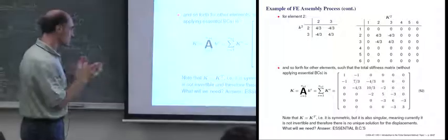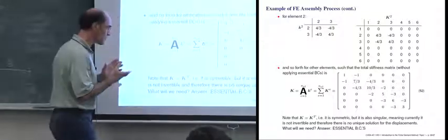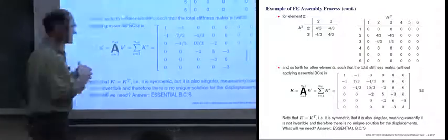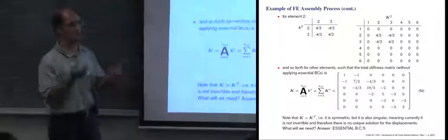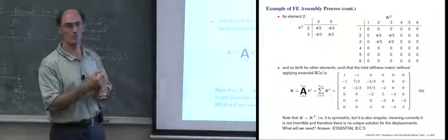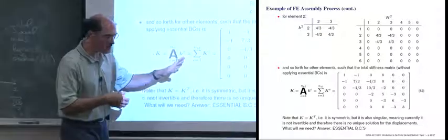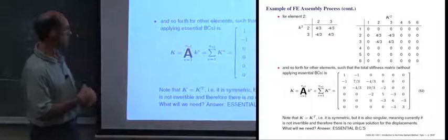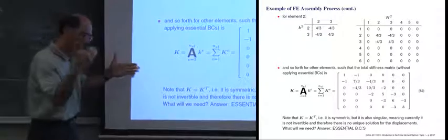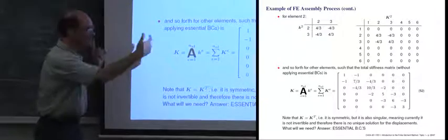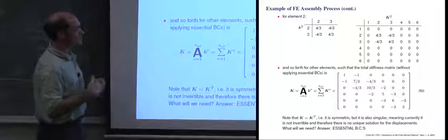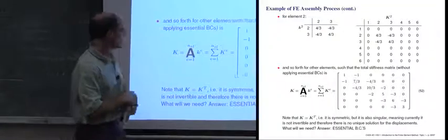But you'll notice one thing. We'll get to it in a moment. But we have a problem. This matrix is singular. So we can't invert a singular matrix. We can't solve Ax equals b with a singular matrix. So we'll get to how that will not be singular in a moment, how we're going to apply our displacement values being 0 at 1 and 6, and some other things.